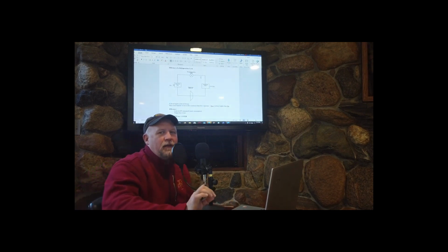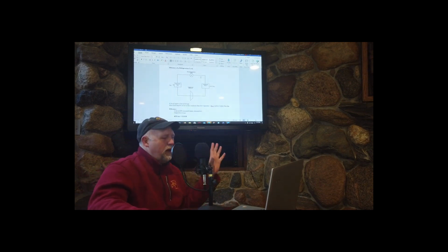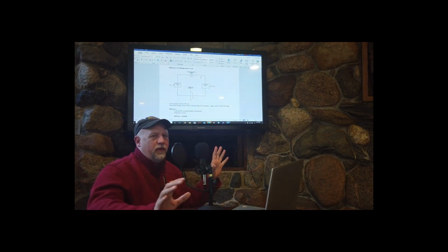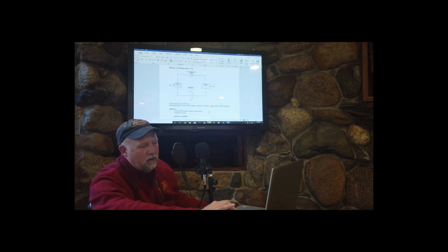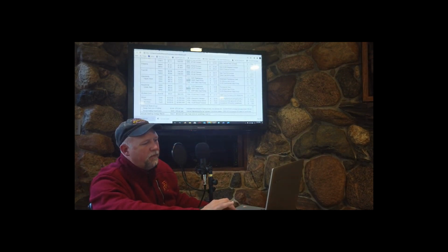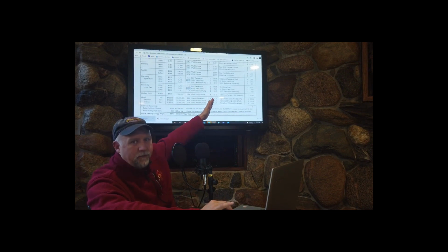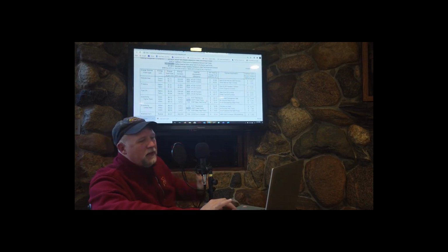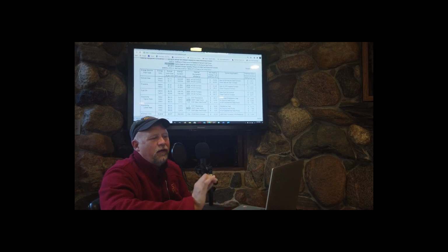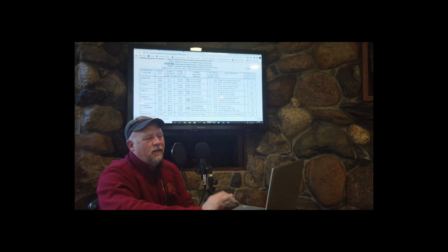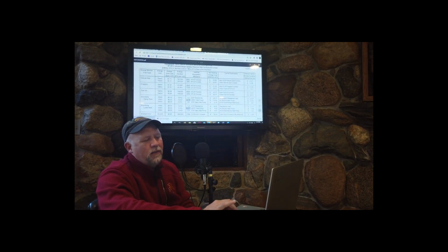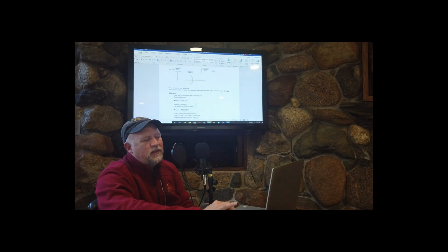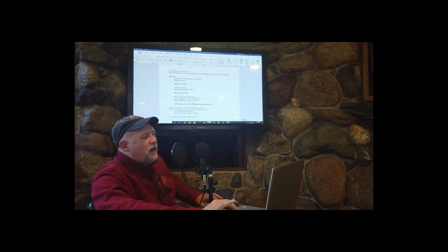The best way to compare one system to another is like this other page, in dollars. That is the best way to compare efficiency, and that is dollars consumed per million BTU of usable heat within the space. And that's the way an owner is going to be able to understand it best themselves. But I want to explain these coefficients.